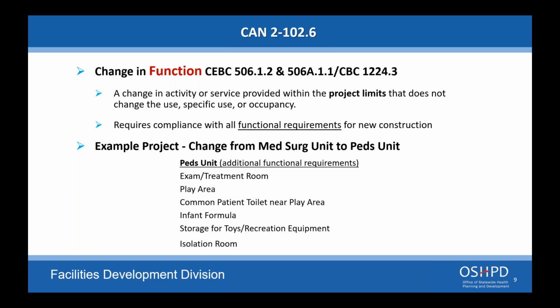Great. Here's a next question for you, Richard. If you need to replace the windows on an existing hospital that are leaking, do we need to comply with Title 24? My concern is that the window to wall ratio will be non-compliant as patient rooms need large windows on all sides of the building. The answer is no. If you're doing a remodel, the energy requirements do not apply to healthcare facilities for alterations. I thought you were going to go with accessibility there, but I think it's 141 in the energy code. It exempts all licensed healthcare facilities for alterations currently.